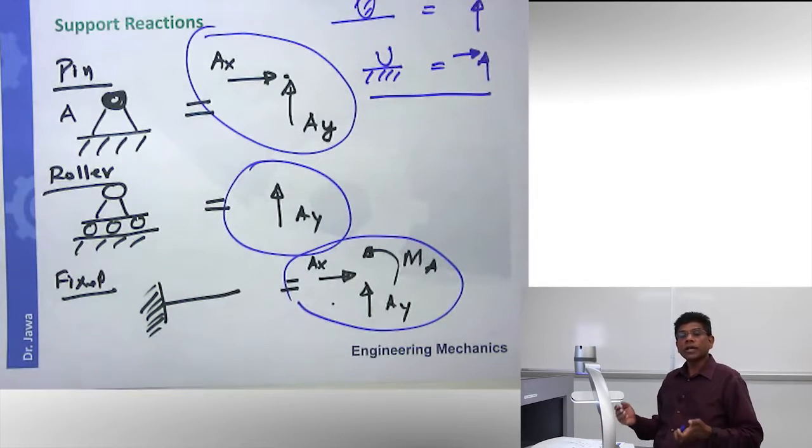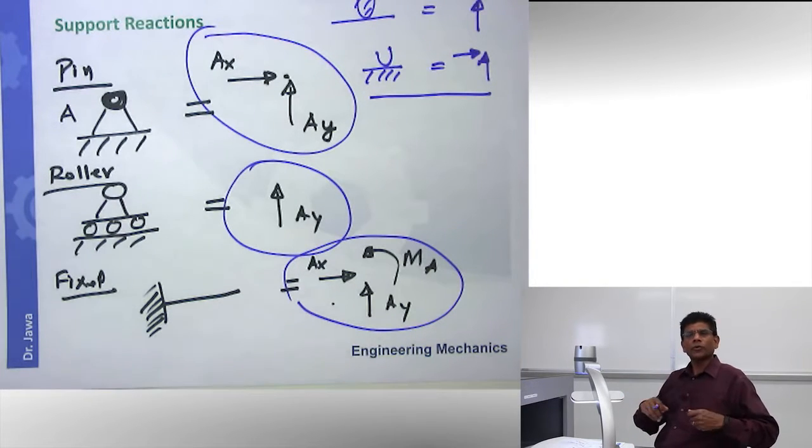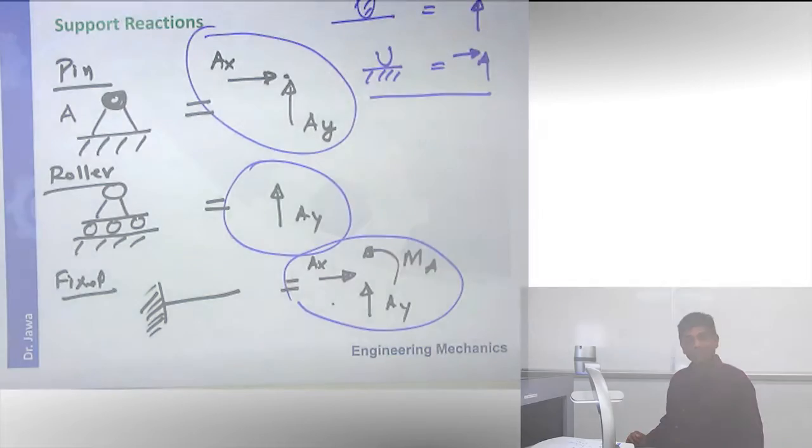These are all the supports that I want you to keep in mind. There are numerous other supports. Cables are another support that we discussed a lot. When you are dealing with a cable, there is always tension in the cable. Therefore, you know the line of action of the force all the time. So these are all the popular supports. Now take a look at an example that involves these supports, and we will solve for support reactions.